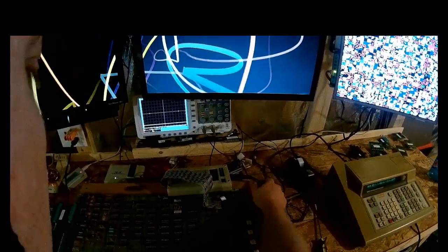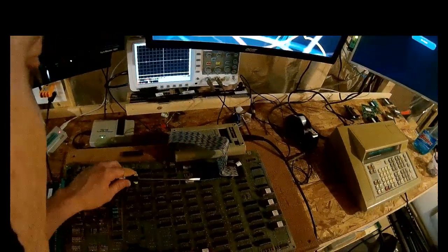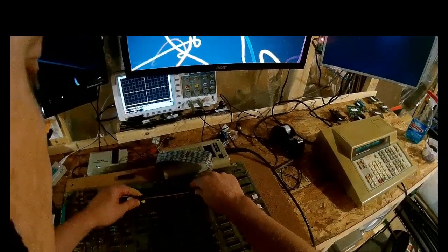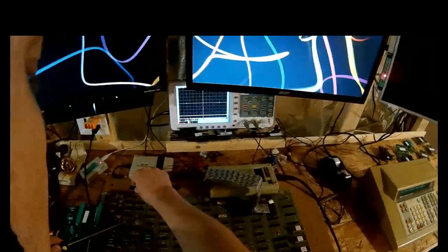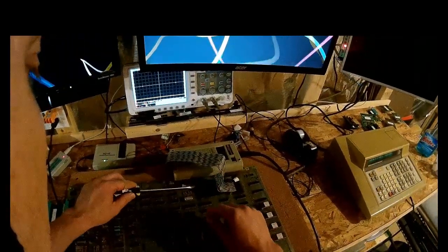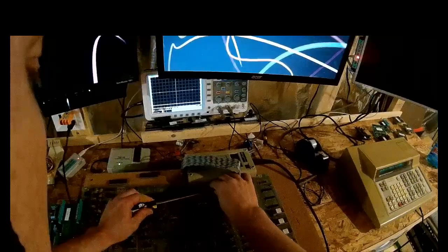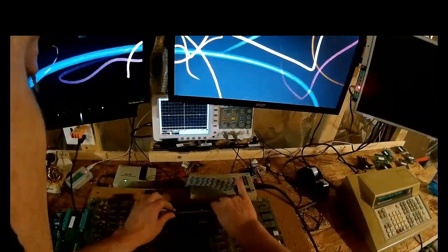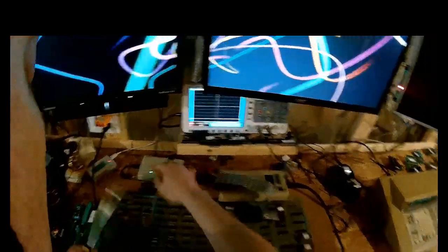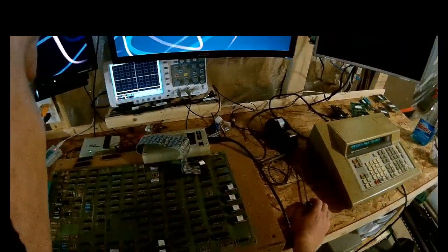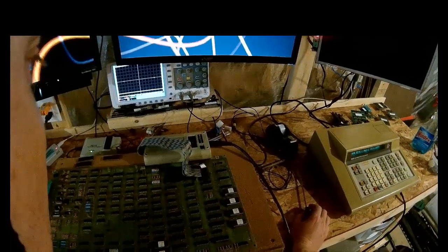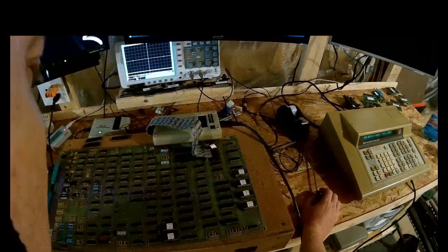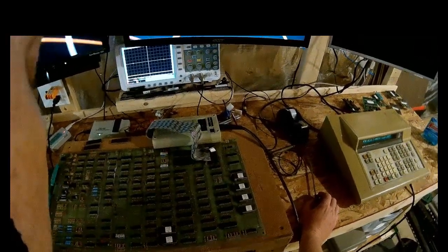So, whenever working on any game with pokies, I like to remove the pokies. Because they do fail often, and they will mess up things. And most games will run just fine. Well, they'll boot without the pokies. The game won't work 100% correct. Like Centipede, it'll boot. You just will have mushrooms on the left side of the screen, and you won't have any type of sound. Millipede, I think, does the same thing. I don't remember. There's 2 pokies on Millipede.